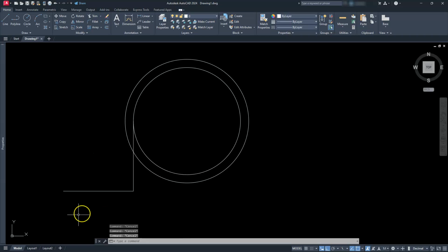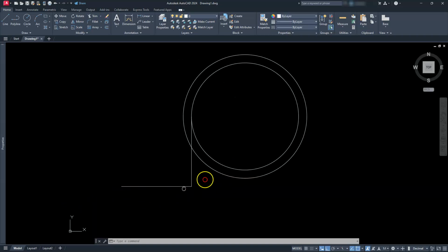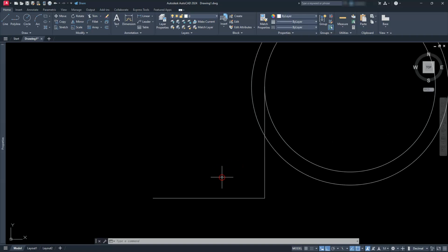Alright. I'm going to do the exact same thing on the other side. Or if you choose to, you can go ahead and mirror this. Alright, but I think I'm going to wait on that. Now that I think about it, I'm going to go ahead and finish this whole entire side here, and then I think it'll be a lot easier for us just to mirror that in one step. Alright, so let's take a look at just dealing with this side. Let's go ahead and offset our distance, which is 1. So offset 1.